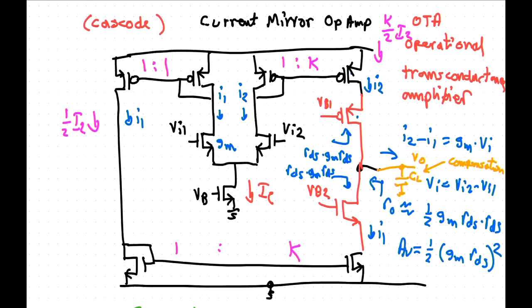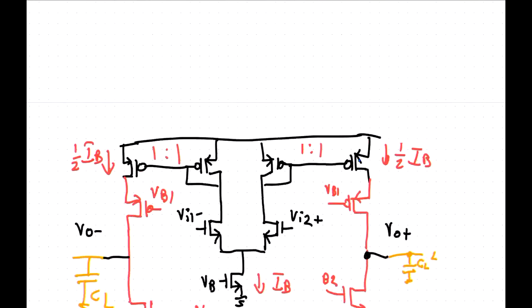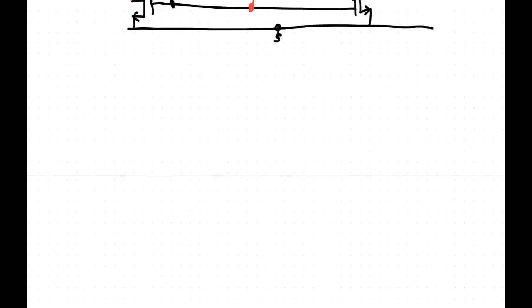The way we normally model that is referring it back to the input, saying we just compensate for that by having slightly different input voltages, and that's the offset error. There's a feedback path from the output back to the input, so it still works because we have the feedback. However, if we look at how to make a fully differential circuit up here, where would you go?